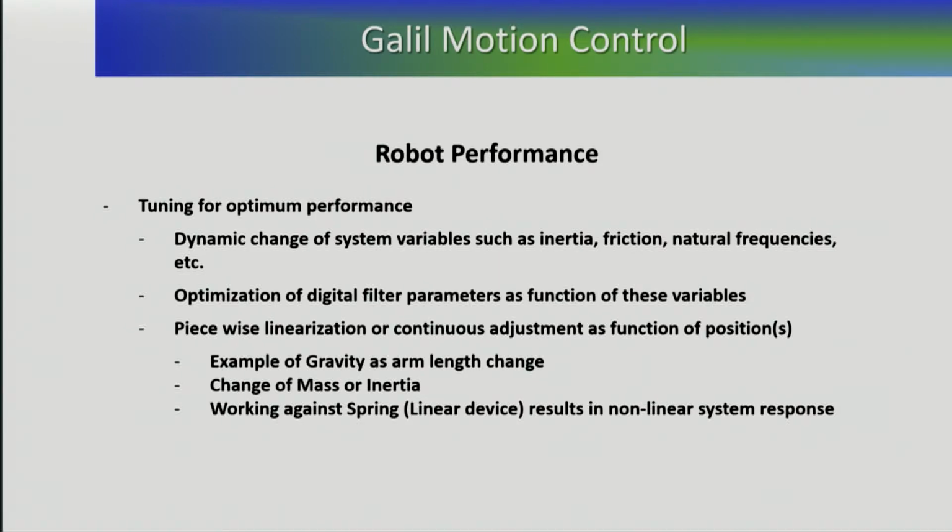Those changes would be reflected back on the motor. Using different transmissions and gear ratios, you can minimize the impacts because you take advantage of the square of the gear ratio against the reflected inertia. So if you have a high inertia, the high gear ratio would reduce the impact seen by the motor itself.